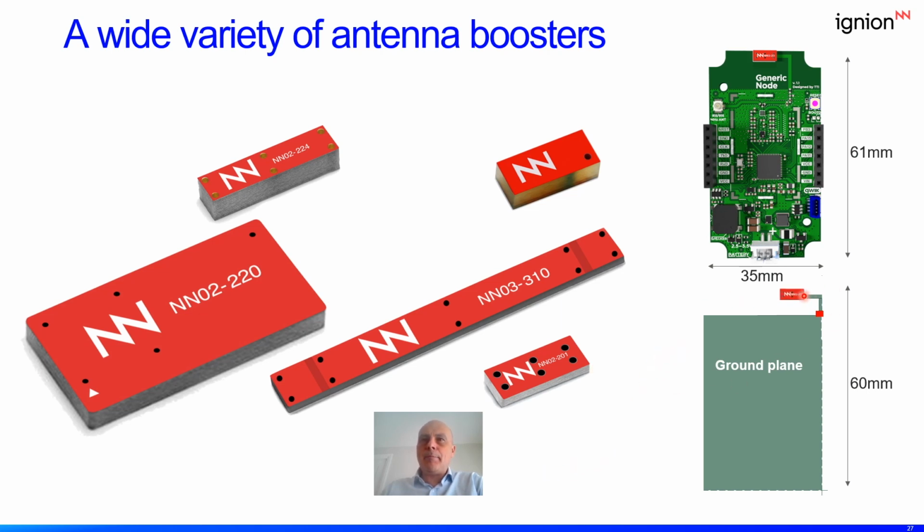So this antenna booster with this ground plane looks very much the same as the device you have in mind at the very beginning of your project. This library contains the S parameters for this scenario without any matching network. Now it's up to you to test in a very simple way if you can get enough bandwidth for your application.